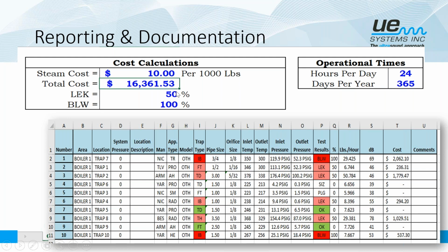Now you can generate the same report through the app, so it's just a personal preference as to if you're using, say, an UltraProbe and then storing that data and then downloading it into the software, or if you're using, let's say, the UltraProbe 3000, which doesn't have the ability to actually load a route into it, but yet we can still go out and test steam traps. Well, we would just need a little spot radiometer, our UltraProbe 3000, and then our steam trap app.